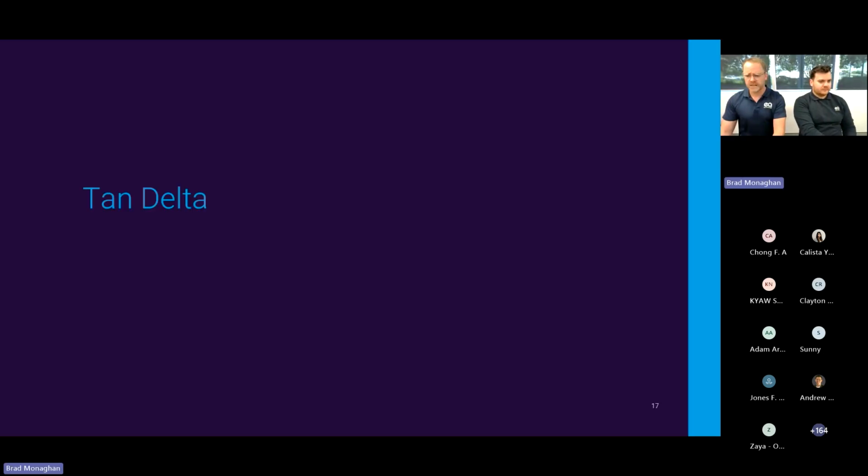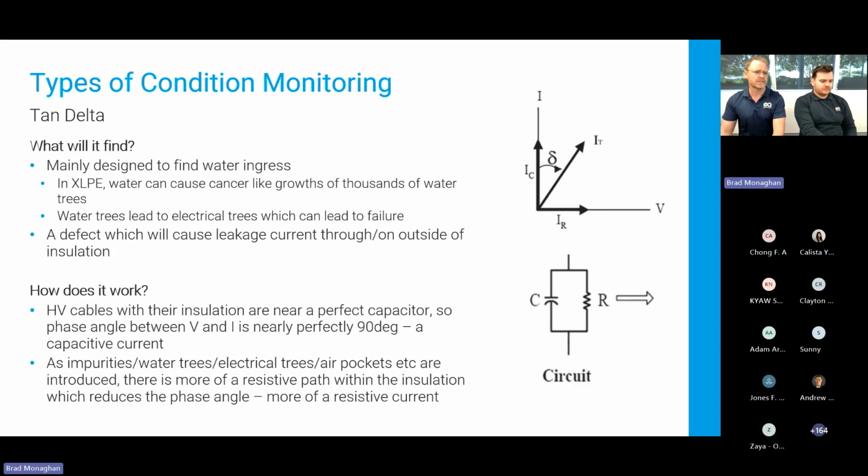Okay, so let's get into tan delta testing. What does tan delta testing find? Tan delta testing is mainly designed to find water ingress into cables, especially your XLPE cables. In XLPE, water can get in there and cause cancerous-like growths in the form of many thousands of little water trees, and these water trees get bigger and bigger over time. It does take a long time for them to get bigger and worse, but what can eventually happen is the water tree gets bigger and longer, and it bridges out a fair portion of your insulation.